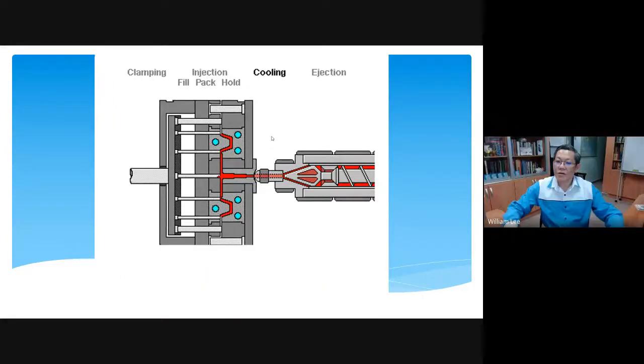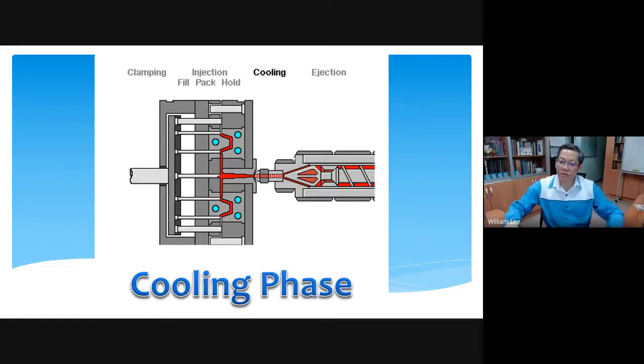Yes, everything okay. Okay. So now we come to the third phase, and this is the cooling phase. Here you can see that during the cooling, this is a water line, right? For the coolant, you can use either water or oil, depending on what temperature you want to apply to your mold. Okay, so during the cooling phase,